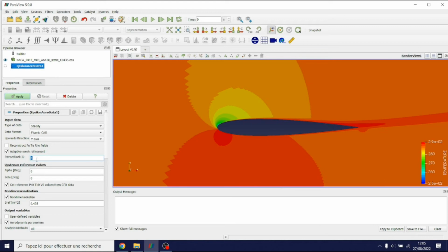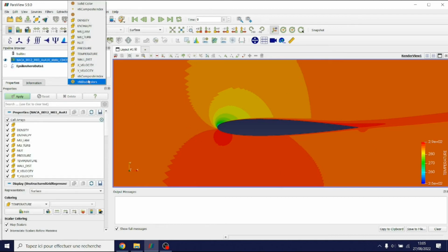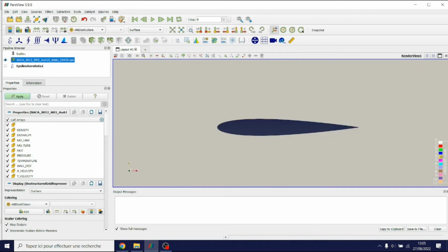As I showed you in the presentation, you will find a gray background block. You can actually color this by block ID, exactly. These are the blocks and all the IDs. As you can see, I have a single block, everything is gray, that corresponds to block 0. If you have some grid adaptation, you will have some other colors corresponding to the other blocks. Well, all these blocks have been taken away, so you have to retain just block 0 that corresponds to the entire background flow field.